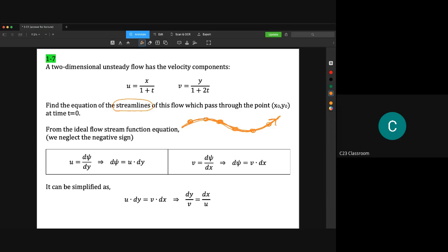So the idea is, certain scientists will take the value of velocity. That's because of the idea of streamlines in simulation work. Let's say in the ideal flow that we revised last week, we have one set of equations called the Cauchy-Riemann equations. In the Cauchy-Riemann equations, the equation starts with u, meaning the subject of that equation is the velocity. u is equal to d psi over dy and so on and so forth.